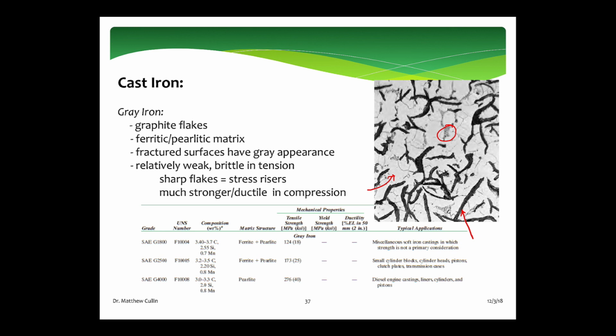Now this is important when we're talking about castings. If you're running a casting operation where you melt down your metal and then pour it into some mold, and the mold can be pretty extensive, how hot you heat your molten metal before you cast it depends on what your mold looks like.